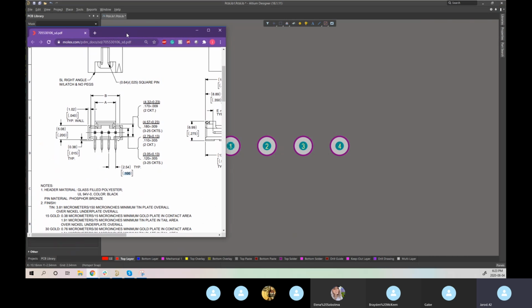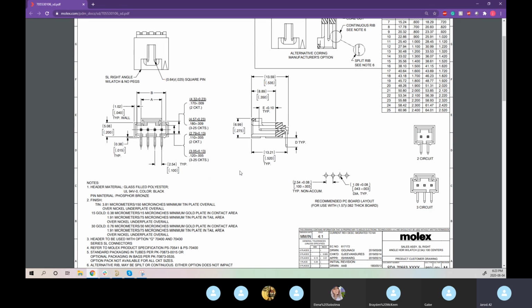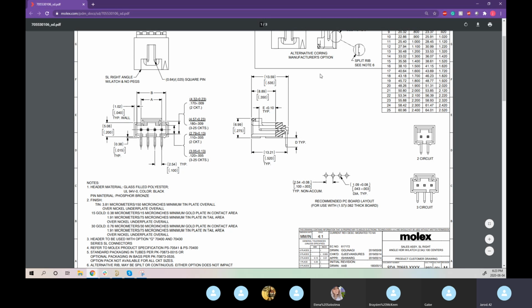Now, the second part to this: there's a couple ways you can go about starting this. You can do it as I did and just slap down the 4 holes at the proper spacing. So you just have the 4 holes set across as they should be, but they may not be the proper hole size yet. And then we can resize these now, or you can start by making sure your hole size is proper, and then throw the 4 across.